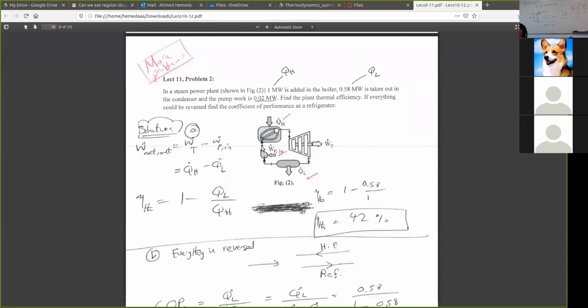So before the boiler, I can give you the input to the boiler: 2 independent intensive properties. So you can know everything about this, if it's an ideal gas or if it is steam, using the steam table. The same for the output. I can give you 2 independent intensive properties, so you can get everything here and there.